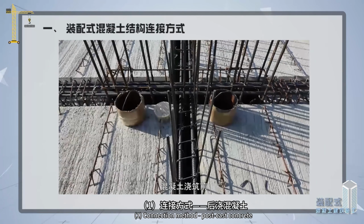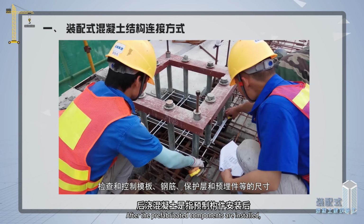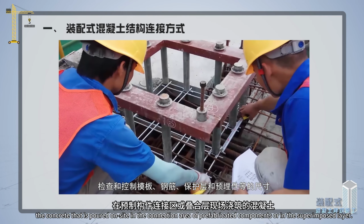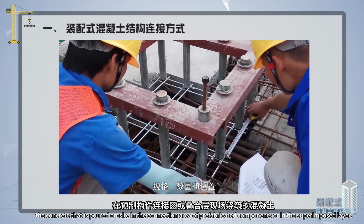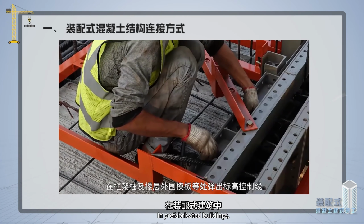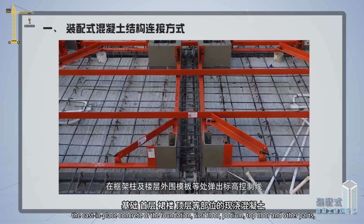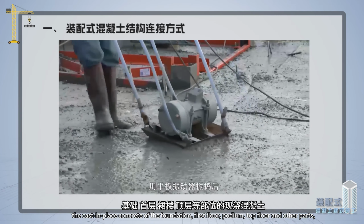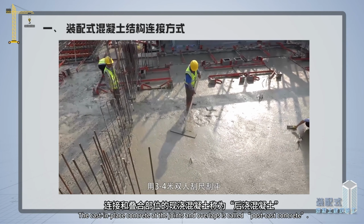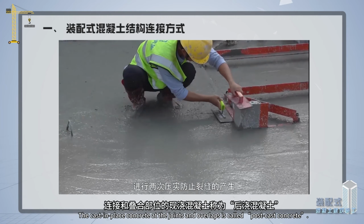1. Connection method: post-cast concrete, after the prefabricated components are installed. Post-cast concrete refers to the concrete that is poured on site in the connection area of prefabricated components or in the superimposed layer. In prefabricated buildings, the cast-in-place concrete of the foundation, first floor, podium, top floor, and other parts is called cast-in-place concrete. The cast-in-place concrete at the joints and overlaps is called post-cast concrete.